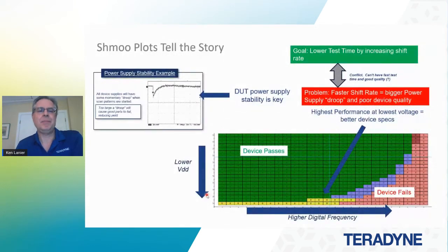If you want to find out how big an issue you have, typically what we do is we look at Shmoo plots, and everyone probably understands what a Shmoo plot is, but typically what happens is you just record pass-fail results as you vary parameters, and the ones that are very popular to vary are VDD and the scan shift rate. So the pattern rate, effectively.